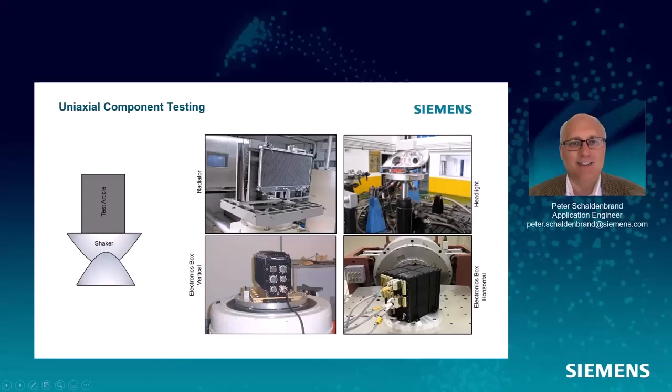Just to give you an idea, typical frequency ranges on these electrodynamic shakers are up to 2,000 hertz. On the hydraulic, 200 would be higher. The advantage of hydraulic shakers is we can put some preload on it and we can get a lot of stroke displacement. These are more displacement limited. Generally, 5 hertz is really low, and I mainly only see it in sine testing, and I see it in qualification, not so much the durability type testing. But 5 is generally the lower end here.